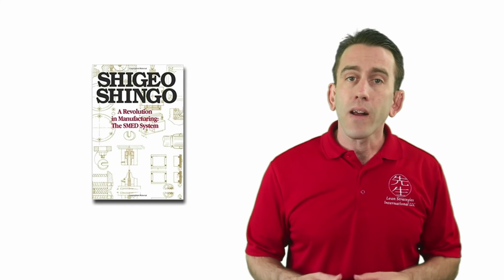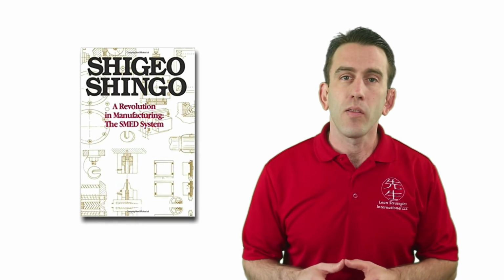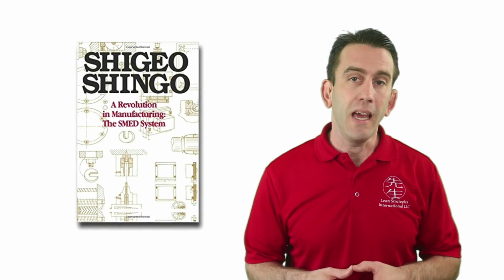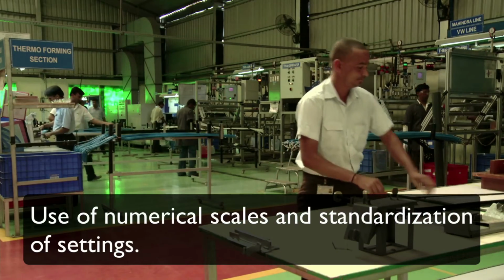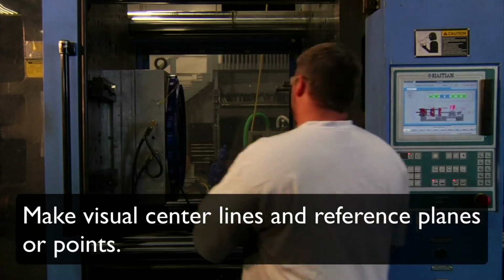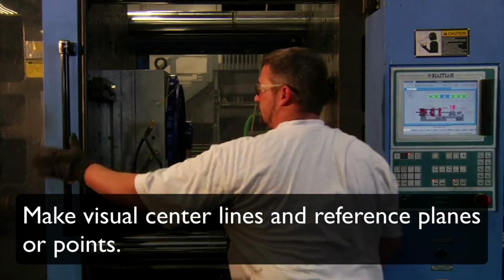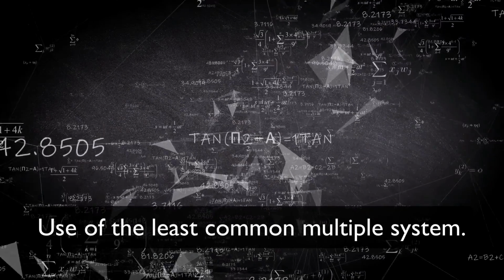There are 3 practical techniques shared in the book A Revolution in Manufacturing, the SMED system, that are used to eliminate adjustments: use of numerical scales and standardization of settings, making visual center lines and reference planes or points, and use of the least common multiple system.